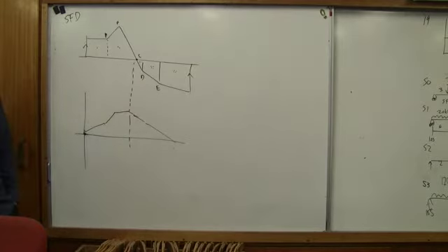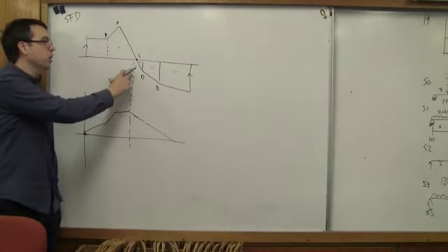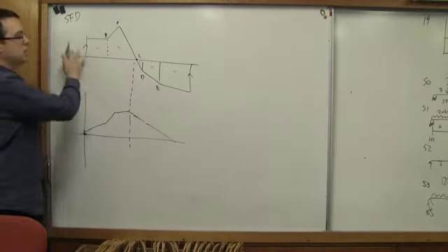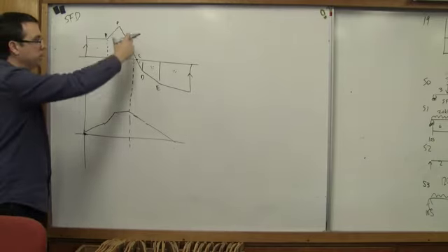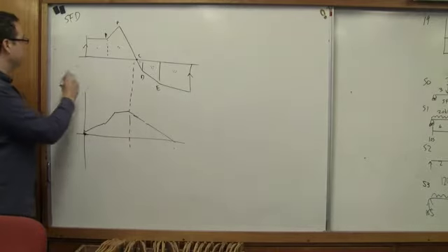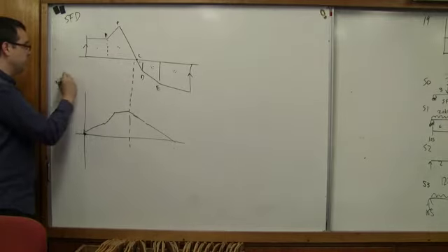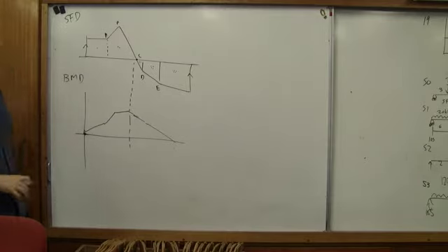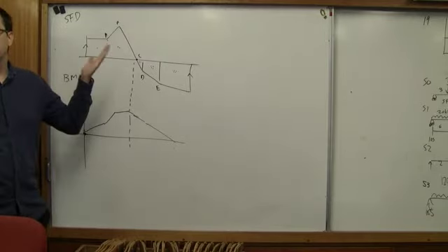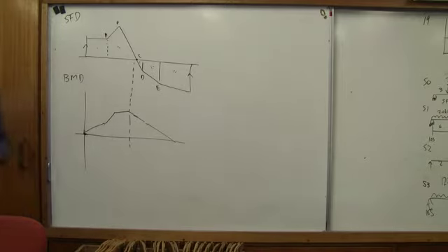The idea is that when you do calculus, you'll learn that maximum values occur where the derivative, relatively speaking, crosses the x-axis. And so in the case for shear force diagrams, our maximum bending moment will occur where our shear force diagram is equal to 0. I would just say that the simple answer is because it crosses the axis, that's where it's going to be, but we just proved it by doing this diagram here. It's hard without values. I just took guesses at things, but we have a rough idea.